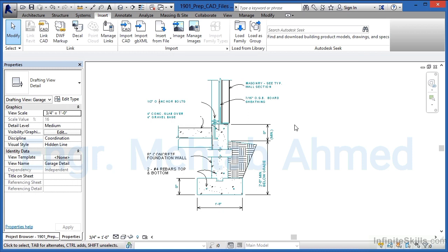Both of these processes sound like they take a long time. The reality of it is that for most CAD details, you can usually completely redo it in less than 5 minutes. The only issue with that is, when you bring in your CAD details, your CAD information, just remember you should always get rid of the CAD information because it's not going to meet your standards. And the second reason is that CAD information can also lead to instability issues in your Revit models.